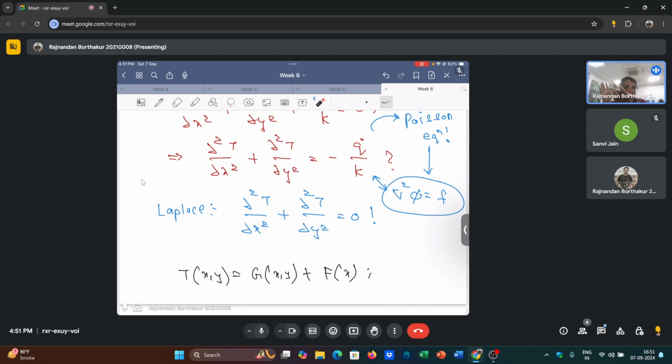Okay, I will show you in the next class how this is basically done, and this has also been shown in the theory classes, but we will just see a gist of it. And by the way, if we use this transformation, you can simply use the Laplace equation, and solve the Laplace equation for g of x,y and just solve the 1D heat generation problem for f of x, and just combine the solution of this.